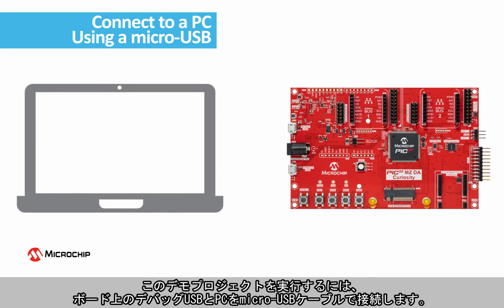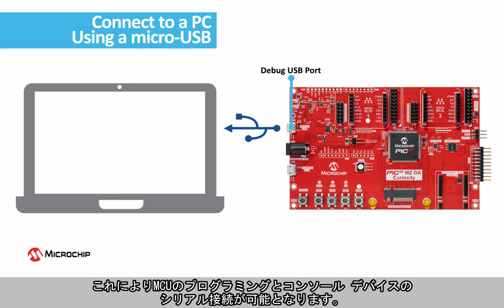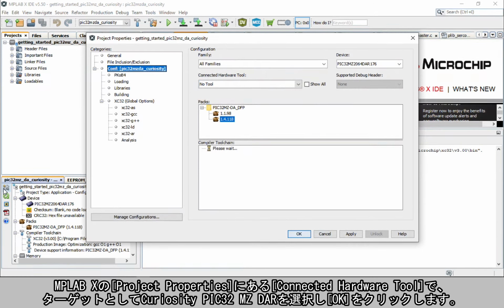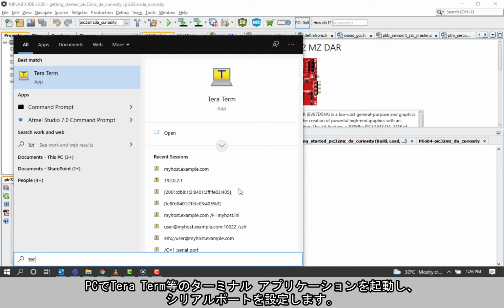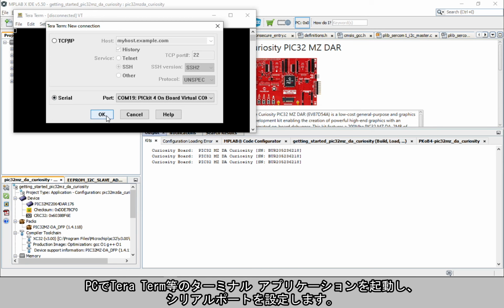To run this demo project, connect a micro USB cable between the debug USB on the board and a PC. This enables the programming of the microcontroller and provides a serial connection with the console device. In MPLAB X, under Project Properties, select the Curiosity PIC32MZ DA as the target kit in the Connected Hardware Tool dropdown. Then click OK. Open a terminal application, such as Tera Term on your PC, and perform the serial port setup.